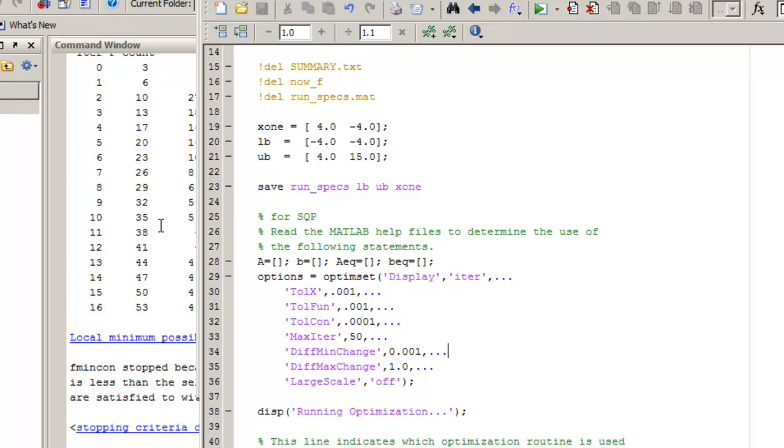So what we've learned is that as an optimizing engineer, you have to not only run your optimization from one starting point, you have to be smart about starting different optimization runs at a variety of initial designs, and then you screen the outputs. If all of them are the same, then you have a really high certainty that that's a global minimum.